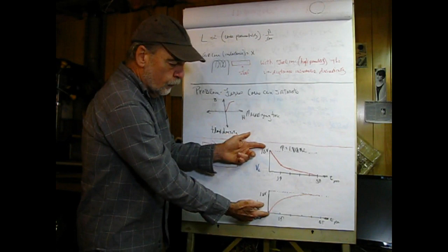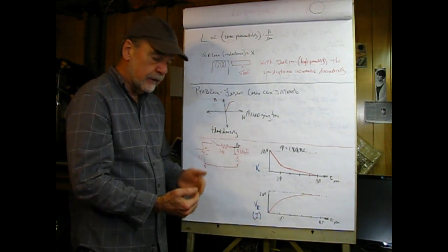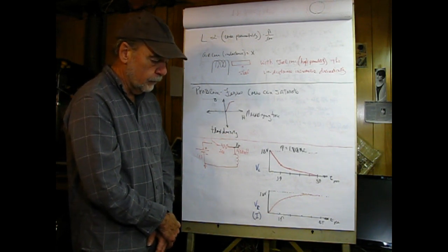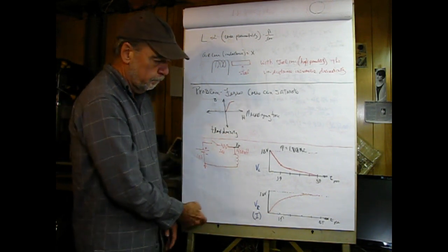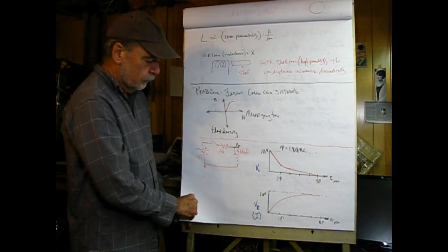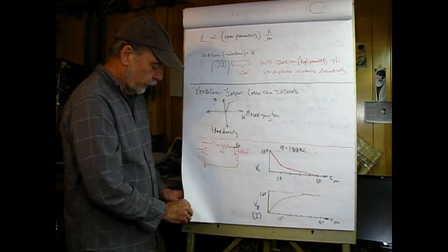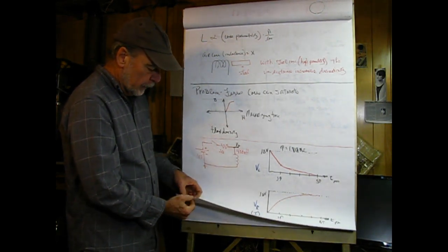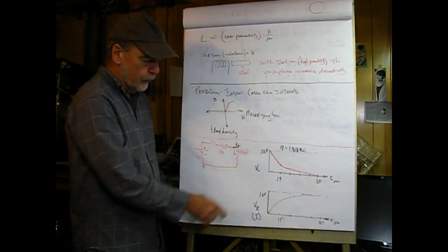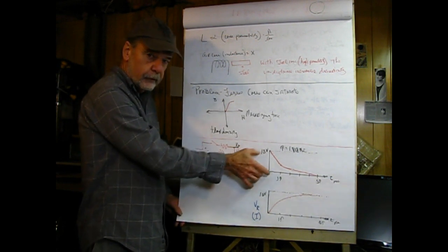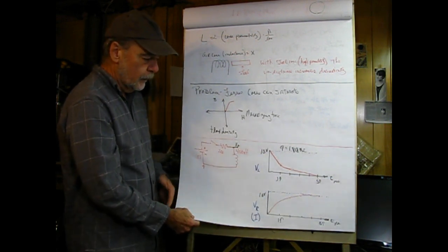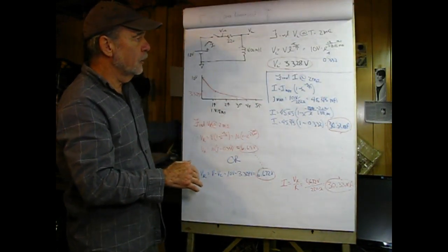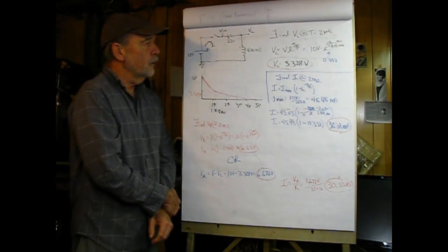If we add these two voltages together at every single point in time, it has to be equal to 10 volts, and that is a function of Kirchhoff's voltage law. One of the things to remember, and we'll have a summary page a little bit later, is that a capacitor and an inductor have very different characteristics when it comes to initially starting to charge them.